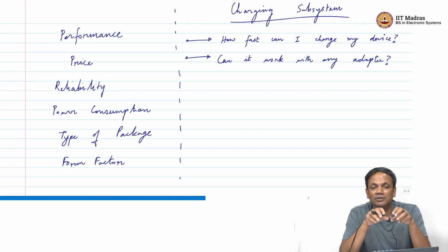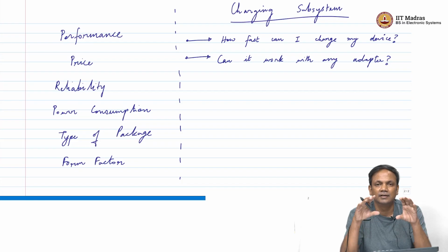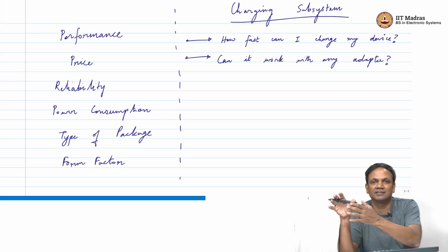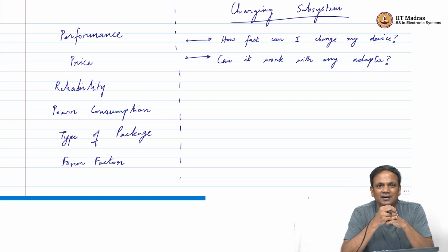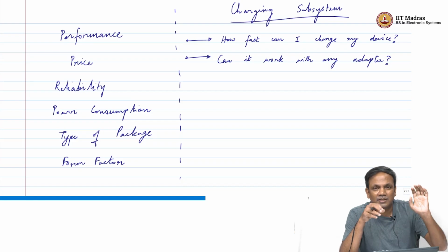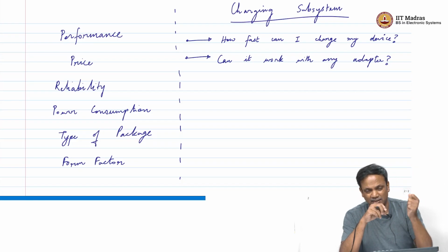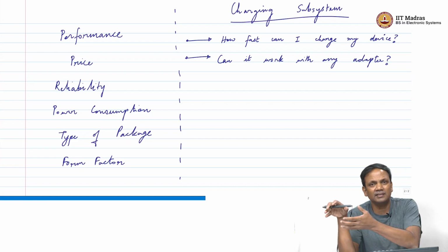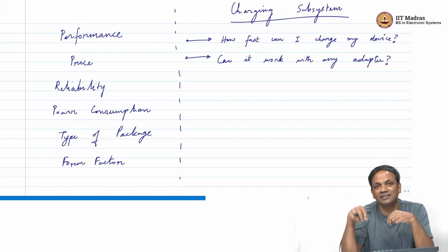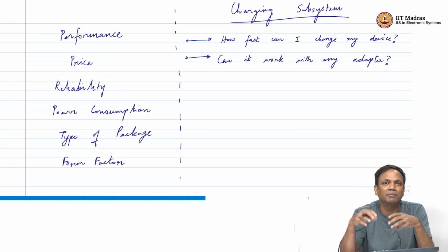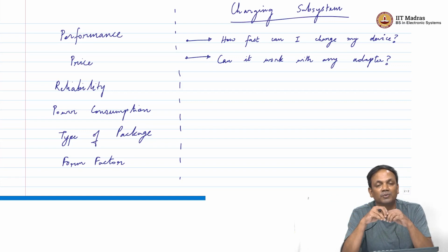You want to be able to say that after all of that conversion, there will obviously be some transient characteristics. You can guarantee to the user that my DC voltage, suppose I am rating it at 5 volt, is going to be 5 volt plus minus something. That is a reasonable confidence. But when you turn on that power supply, when that 220 volt is applied to one end of the coil, what are the transient characteristics that will be seen at this 5 volt output? That is very hard to guarantee unless it is designed well. It is possible that it will come to 5 volt, but for a brief period of time it might go to 15 volt, it might go to 20 volt.